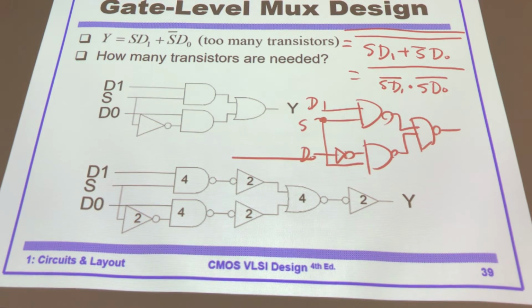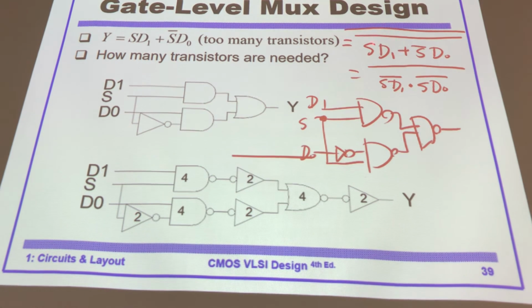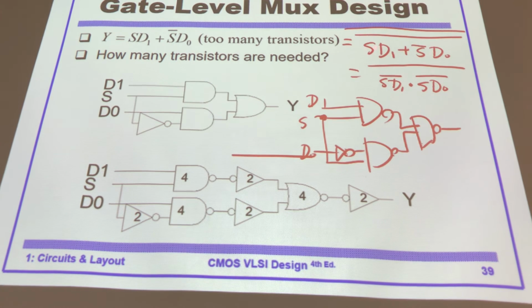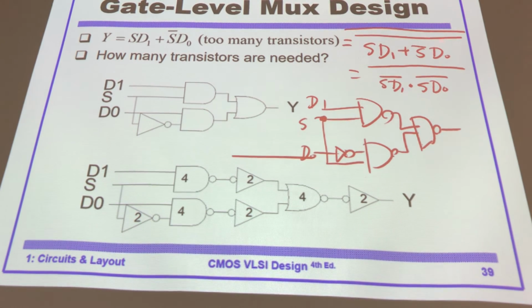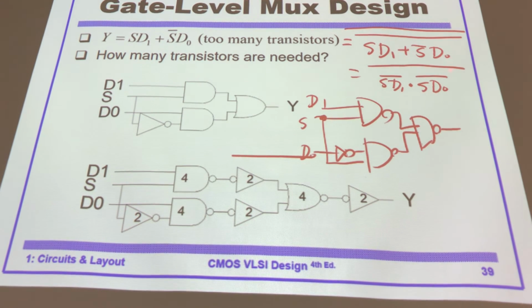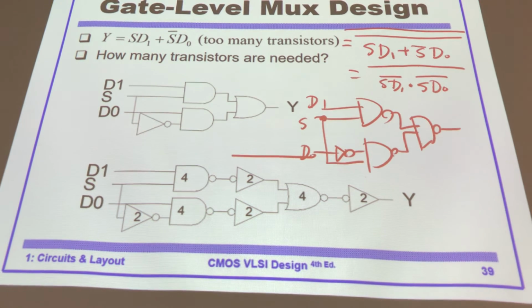Is that correct? You see that? Let's put 2 bars here. It's going to be clear, right? And then apply this bar and distribute it inward. SD1 becomes SD1 bar, the AND becomes an OR, by De Morgan's law, right? And this bar applied to S bar makes it S. These will become this here.